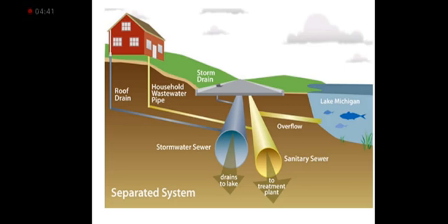Here in this picture we can see we have two pipes. The first pipe is called the storm sewer line. This blue pipe is the storm water sewer. It means this is the runoff pipeline, which is connected at the corner of the road to the drain. Due to the camber, the rainfall falls in this and comes into the storm sewer line.